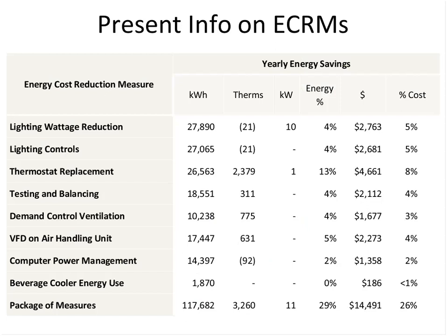Thermostat replacements: we found the building had real control problems with the thermostats, and we recommended replacing all the thermostats in the building. There was one in every room. That's why it's a little costly ECM there, about $4,600. But 13% energy savings based on that.